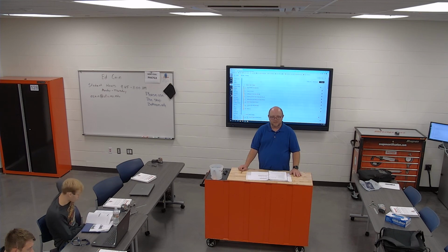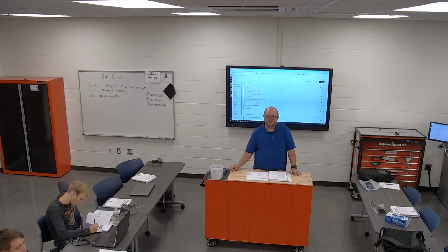Now, say you're going 200 RPM, it's going to be wrong. It'll probably change the answer. I imagine you get 2 different things. It just happens to be because we use 100. 12.5 is what I got when we did that. It was a 3/8-16, so 16. 1 divided by 16 is 6.25. Yeah, so it'd be the same feed rate if it was going at twice the spindle speed.